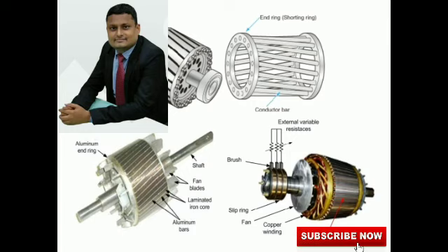Now write down the next question. Design a 2.2 kilowatt, 400 volt, 3 phase, 50 Hz, 1470 rpm squirrel cage induction motor. Efficiency equals 0.8, power factor equals 0.825. Design for low cost. Assume BAV equals 0.44 Weber per meter square, AC 21,000 ampere per meter. Use a star delta starter. You can do this question as homework.